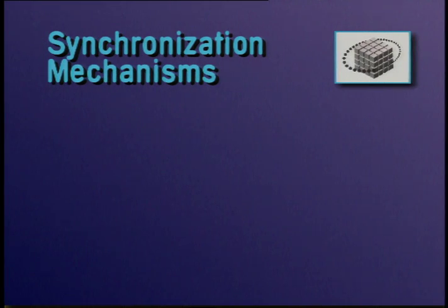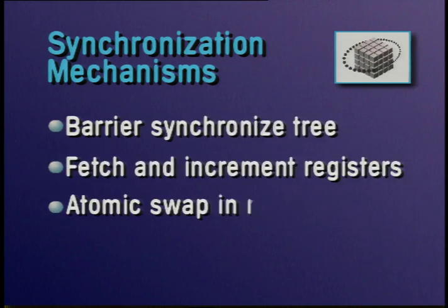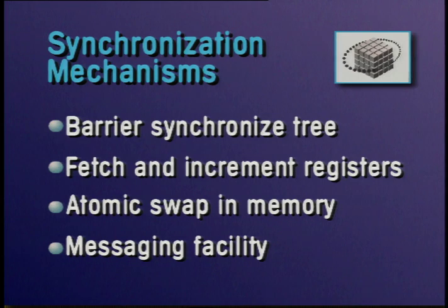The PE shell circuitry implements 4 major synchronization mechanisms: barriers, fetch and increment, atomic swap, and messaging. A barrier is a point in a program beyond which no processor should advance before all processors have arrived. Barriers are often used to delineate between parallel sections of code when data produced by the first section is to be consumed during the second section. It is a block form of synchronization that is latency sensitive, since there is usually little to do while waiting for the knowledge that the last processor has arrived at a barrier to be propagated to all processors so that